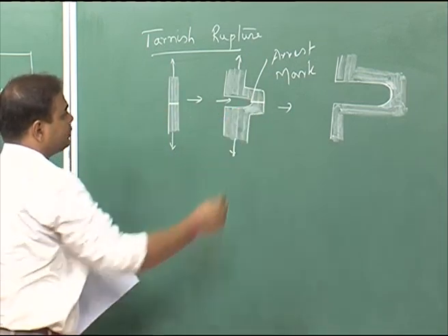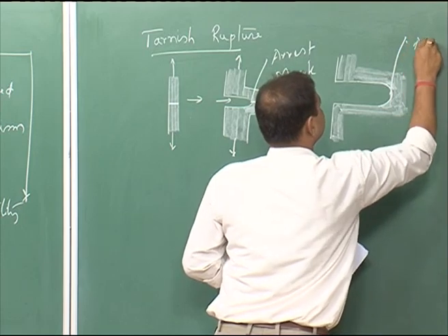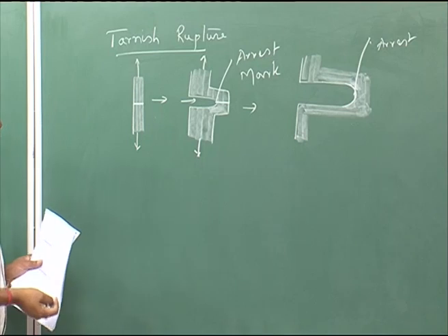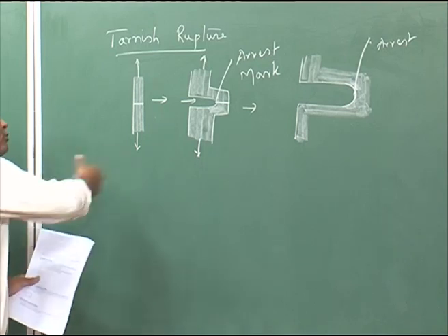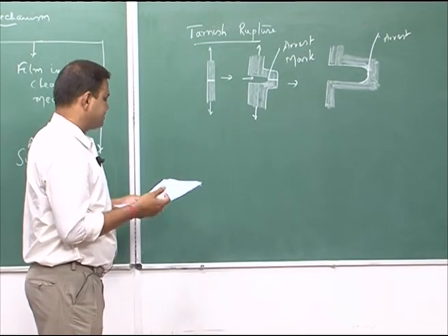Like that way it will grow. So, again here you have a crack arrest. Like that, film forms, film breaks, again film forms, like that it will go on. This is basically the film rupture model, with cyclic growth as well as fracture of film.